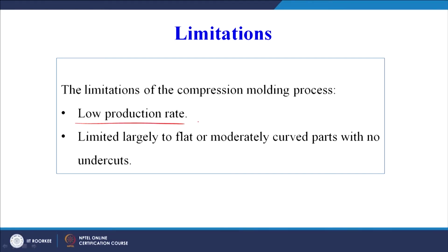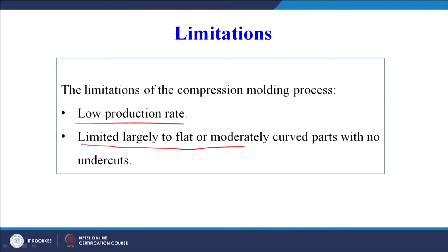So the production rate as compared to injection molding or blow molding is relatively less, and it is limited largely to flat or moderately curved parts with no undercuts. So undercuts in the product design have to be avoided. This is a good guideline for product designers, that if the product is having a large number of undercuts, then the compression molding process is not advisable. Similarly, if the surface is very complex, three-dimensional in nature, compression molding may not be a good process.